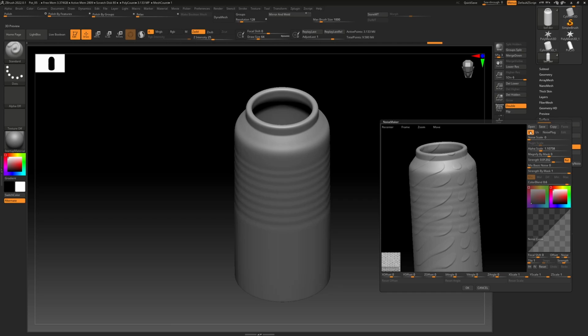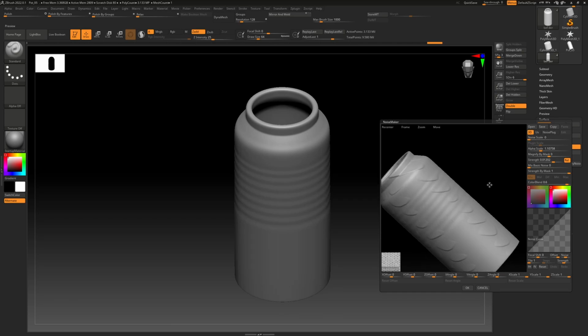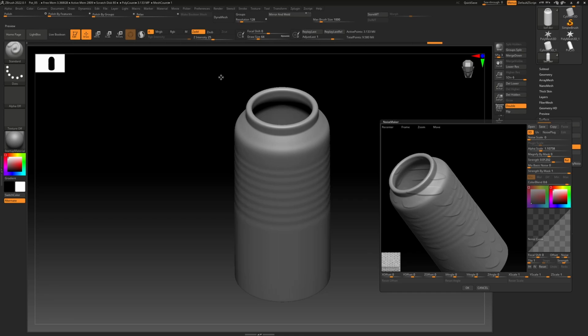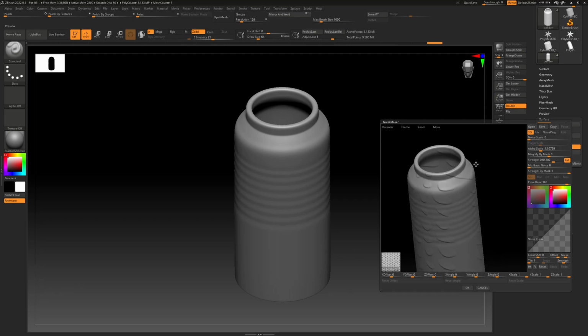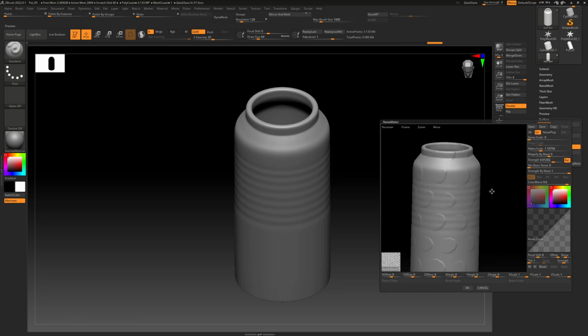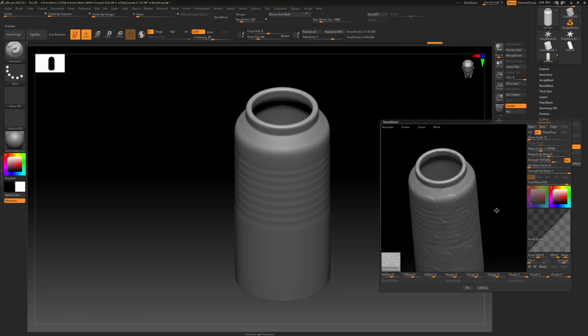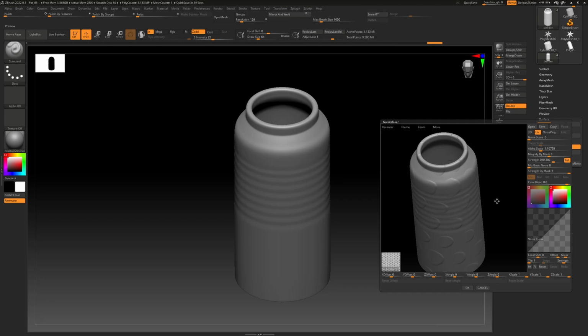Here it is projected according to the 3D scene and 3D model. It is doing a four side projection, like from this side, this side, this side, this side. But we want it according to our UVs, because we have UVs in Maya and they are straight. If I click this, the pattern will align according to our UVs.